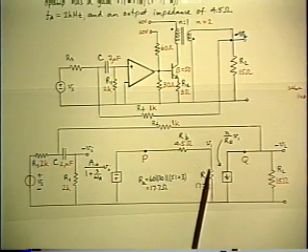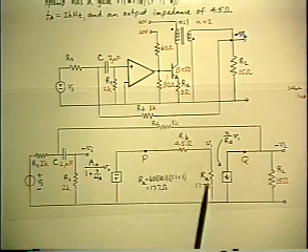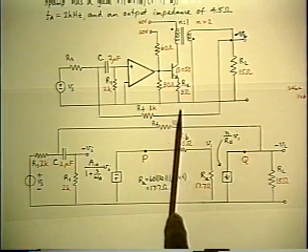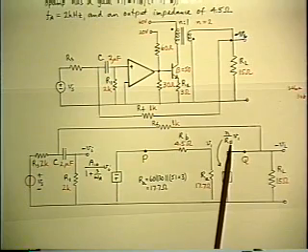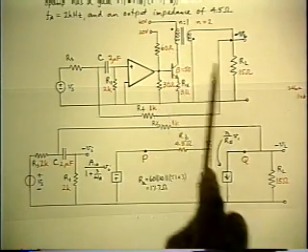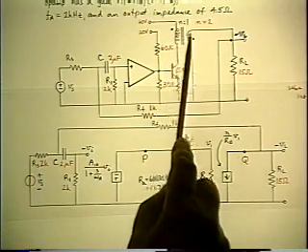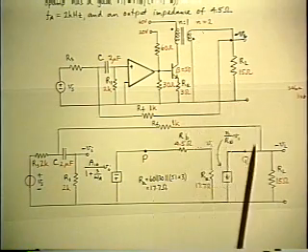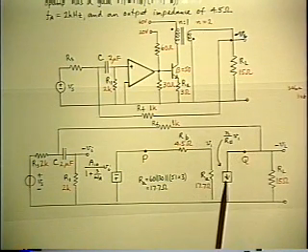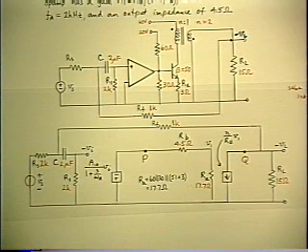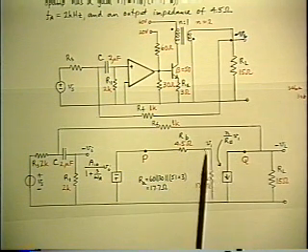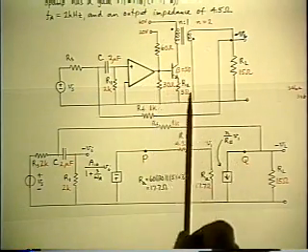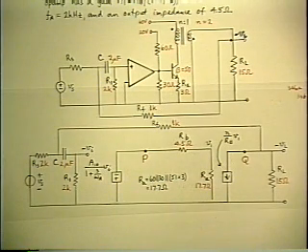So now we've got the representation of the input resistance to the power stage. So V1 is going to develop a voltage across RE of V1 over RE, which will be the emitter current. Multiply that by alpha, which is 1. Multiply the collector current by the transformer ratio, which is N, and so that factor determines the secondary output, and the transformer is included in the current generator coefficient. So the input resistance and the output current is all you need to represent the gain properties of the power output stage.